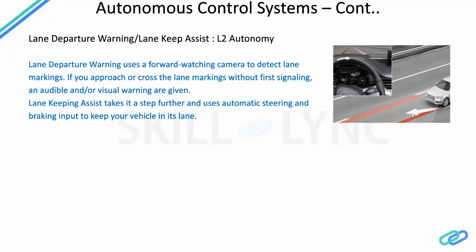Now to control the lateral acceleration, suppose there is a curvy situation and you are going out of the designated lane. To bring you back to the designated lane, the lateral acceleration of the vehicle is calculated, keeping the vehicle dynamics in mind so that you do not skid. If you are at a higher speed, then automatically braking will be done by this model, so that you slow down a little and you steer back properly in the designated lane. Similarly, what you do on a curvy road is, you slow down and then do the steering. So this is automatically being taken care of by this control model.